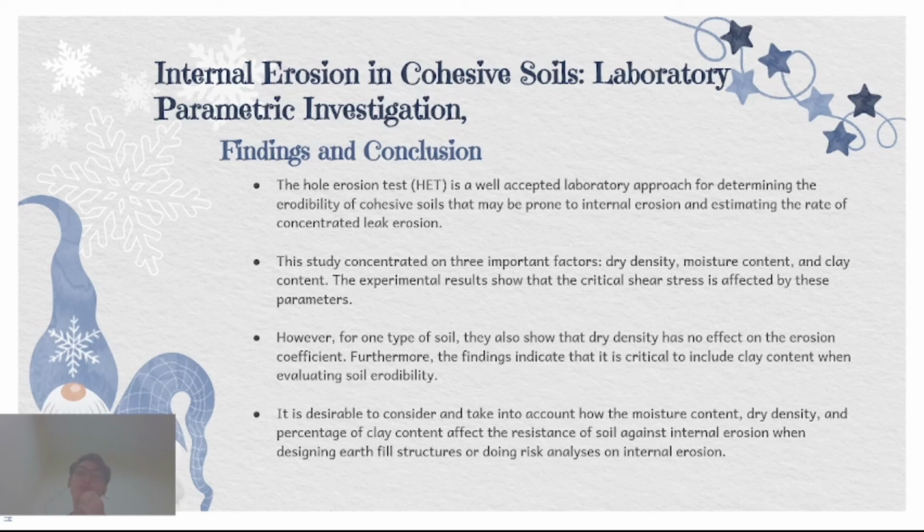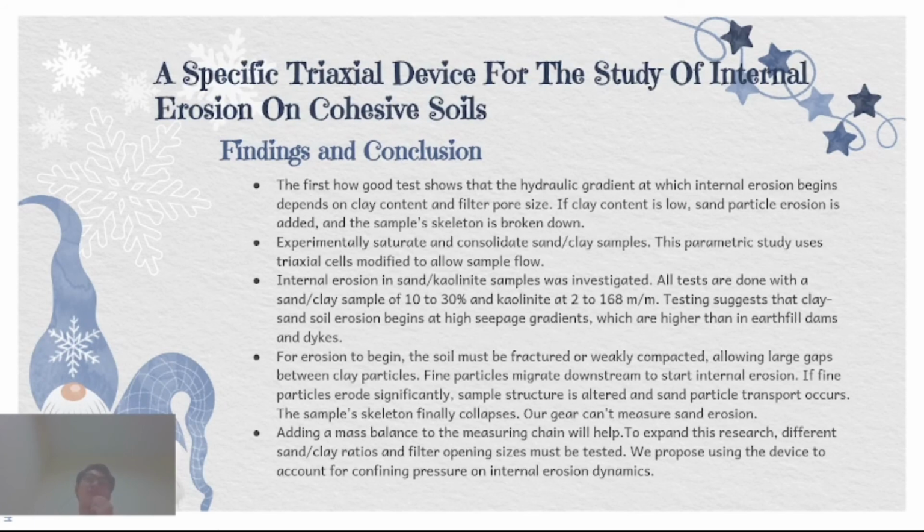The results show that critical shear stress is affected by those parameters. It is important to take into account how the moisture content, dry density, and percentage of clay content affect the resistance of soil against internal erosion when designing earthfill structures or doing risk analysis on internal erosion. So the second case study is about a specific transient device to study internal erosion, and